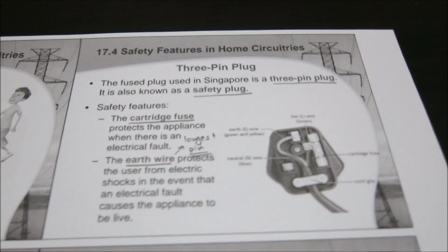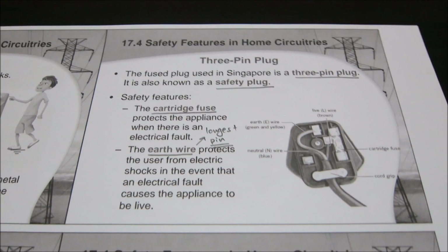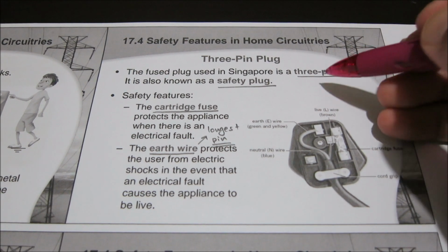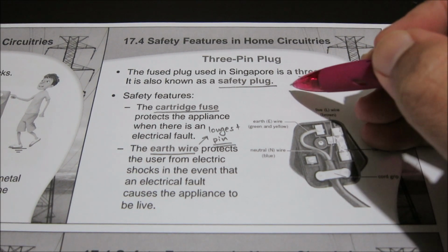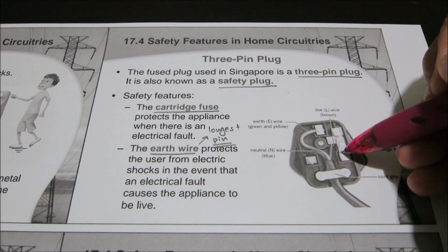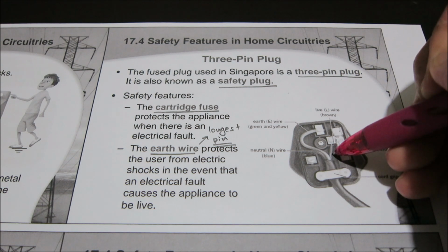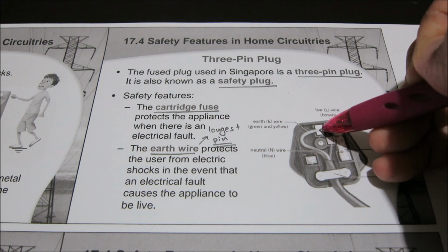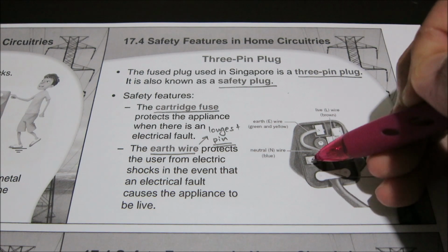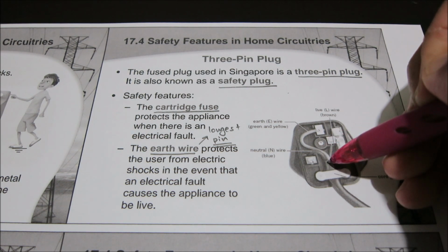Now, the 3-pin plugs. Not all countries use 3-pin plugs. Singapore uses it. It's known as a safety plug. You have the fuse, again connected to the live pin, red wire. The earth pin, the longest pin, connected to the earth wire, and the neutral pin, the blue wire.